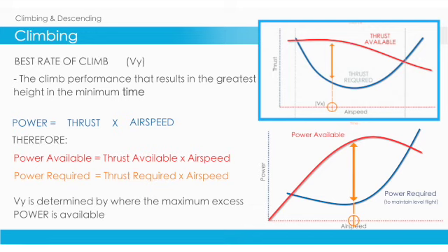Just to add some more data to this graph. Thrust available started high and slowly went down. Thrust is at its maximum when the airplane is not moving. This is because the engine is at full output and the backwards pushing force is at its maximum. Once the airplane gets fast enough, the pushing force from the engine and propeller is not enough to push the airplane any faster. It's already pushing it through the air, and it's at maximum output, so it has no more thrust, or force, to give.